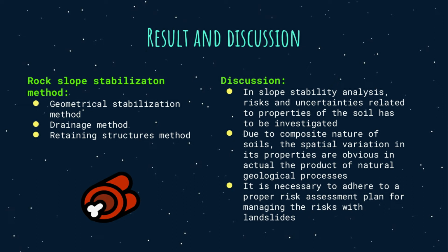The saturation and pore water pressure built up in the subsoil is one of the slope failure reasons. If a drainage system has been installed, the risk of pore water pressure and subsoil saturation increasing would be reduced. This strategy has the potential to be incredibly effective. However, the drainage system must be maintained in order to function properly. The surface drains are easy to manage while the subsurface drains are more challenging.